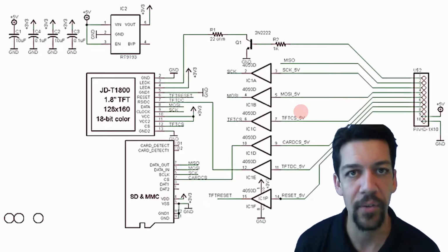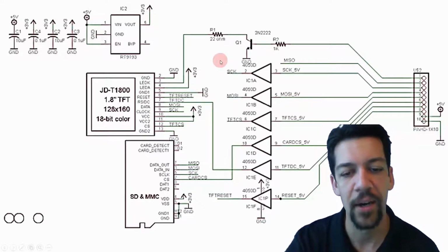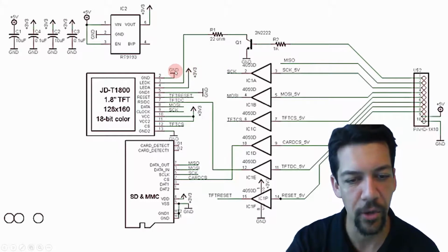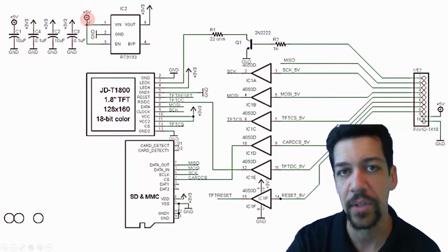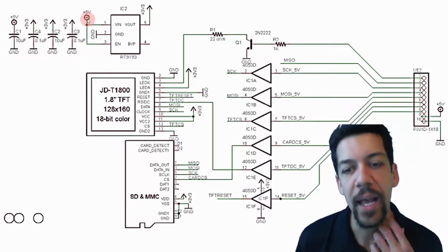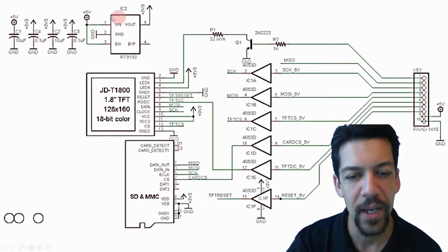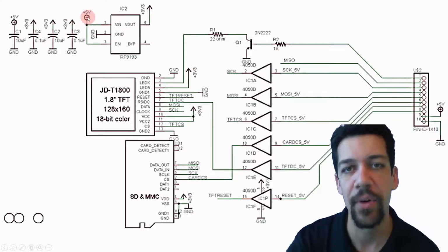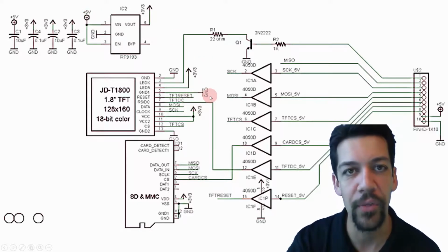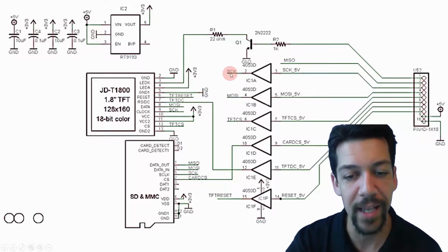Here's an example of a circuit that has 3 different kinds of supply signals. There's a 3.3 volt, there's ground, and there's a 5 volt too. So this circuit is working between 2 different kinds of voltages. And you'll notice some other signals as well. The supply signals tend to have their own symbols that represent a connection, but for things that are just regular signals that we need to connect together, we just name them and then end the line.